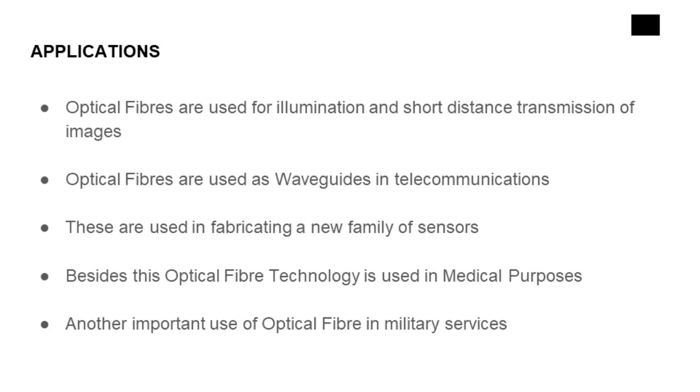A smoke and pollution detector can be built using optical fibers. A beam of light radiating from one end of the fiber can be collected by another optical fiber. If foreign particles are present in the region between the two fibers, they scatter light. The variation in intensity of light collected by the second optical fiber reveals the presence of foreign particles.